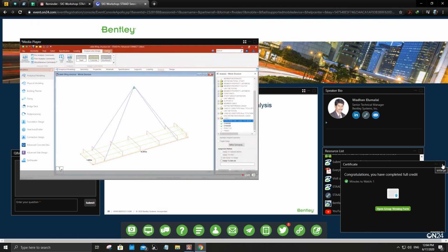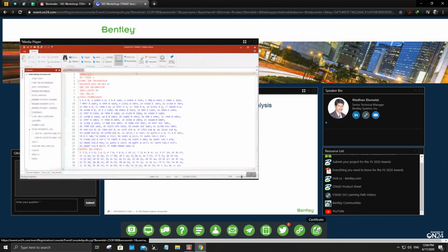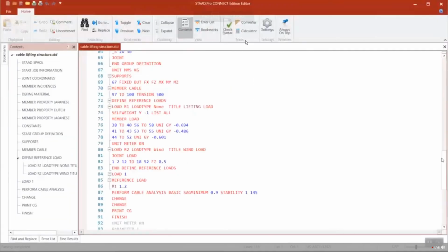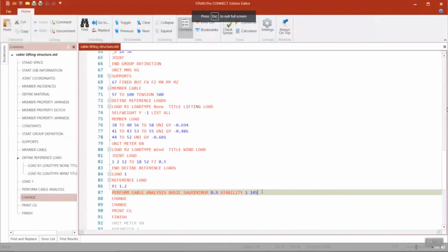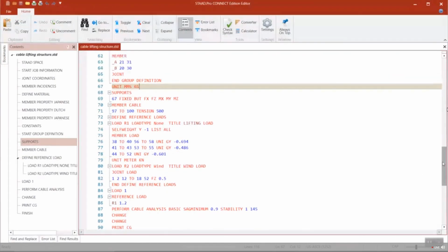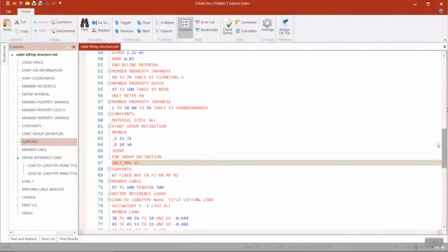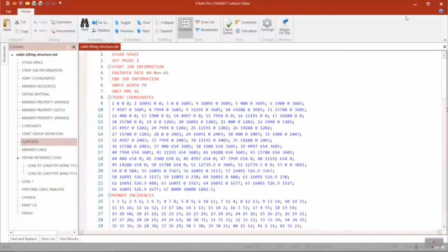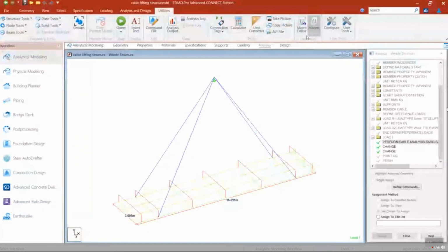And the loads are modeled using reference loads. So for lifting analysis, you have to use reference loads. Otherwise, you can model one primary load case with all the real load cases in it. Okay. Don't analyze this lifting analysis for unreal load cases like wind load acting alone. The structure will never converge.